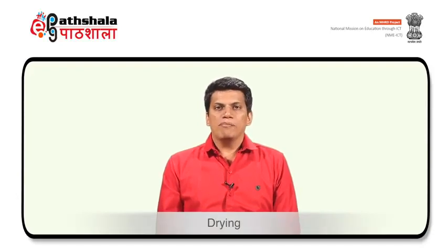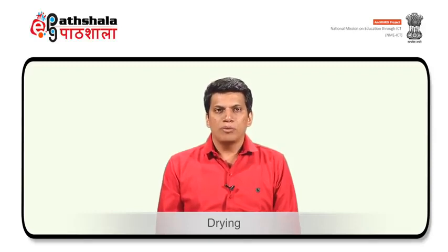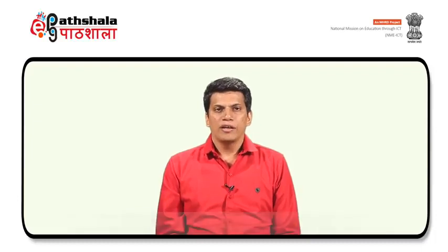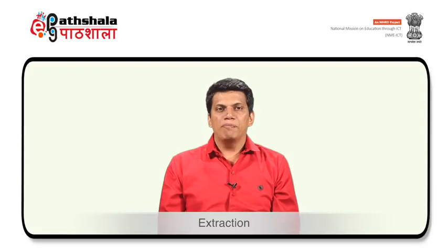The next process which is affected is drying. The drying of wet masses may be facilitated by size reduction, which increases the surface area and reduces the distance that the moisture must travel within the particle to reach the outer surface. During tablet production by wet granulation, the sieving of the wet mass is done to ensure more rapid and uniform drying.